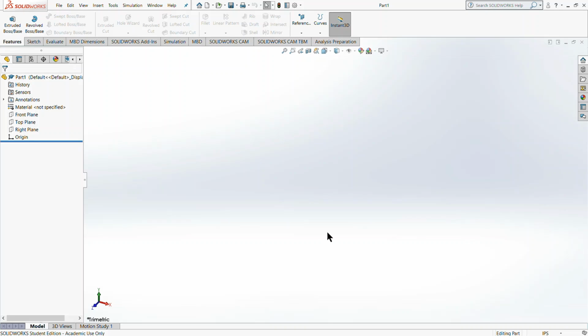An assembly, on the other hand, is a conglomerate of parts. It's unified parts. What helps with this format is you could edit your parts by themselves however you'd like, and then finalize them. Once you go onto an assembly, you can pretty much paste in those parts and join them together and make one unified model without having to draw the whole thing from scratch. It helps with organization and file conventions. Lastly, you have drawings, which are essentially the engineering grade drafts that you're going to be submitting towards the end of this class. We'll cover those in a later video. But for the purpose of this video, I've selected a part.